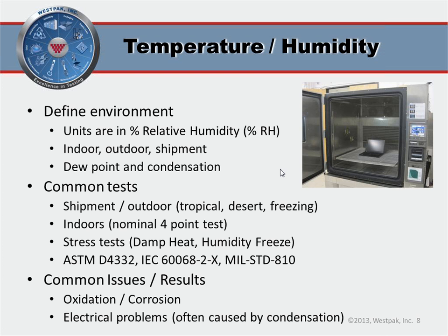One thing we have to be concerned with is condensation. Condensation occurs when a product is below the dew point. An example of this would be a cold drink getting water forming on its coaster. One more tangible example, though, is Florida in the morning in the summer. A typical weather condition may be 27 degrees C, which is very comfortable, and 85% relative humidity. At that condition, the dew point is only 24 degrees C. So if you're even slightly cooler than the air temperature, condensation will form on your product.